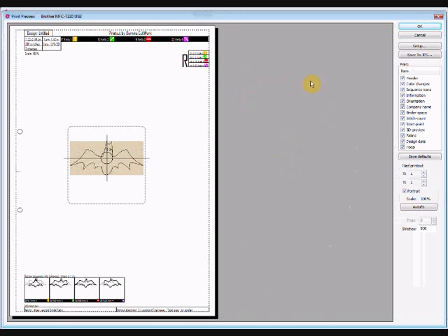And on the print preview page, you get a preview obviously of what you are going to create, and you'll get a picture here of your design. Up here it's telling you what the knives are, so that's basically a header. In here it's the order of the knives. Down here you've actually got a picture of which bits are going to cut with which knives, and the knives are underneath them. And you've got other sorts of information, and all that information is defined by which of these boxes over here are checked.